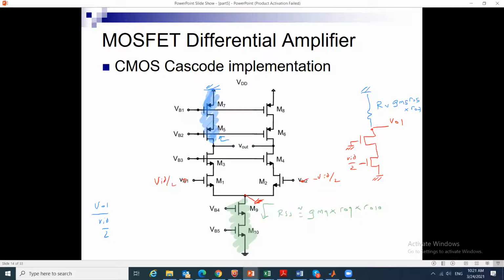Yes. Professor, what did you say is the resistance looking up into the M5 or M7? And shouldn't it be RXY, I guess? Yes, it is an RXY. So the RXY is really GN times RX times RY plus RX plus RY, right? We are just, for brevity and because sometimes it is dominant, taking this term here. All right, thanks. We definitely want to include this, but as an approximation, it will be this. Thank you. Okay, anybody has any other questions?